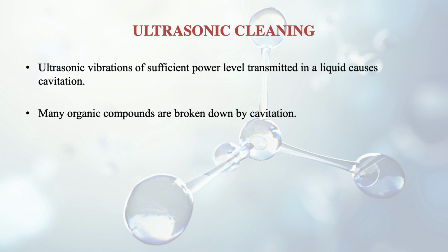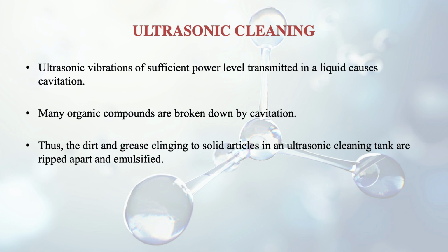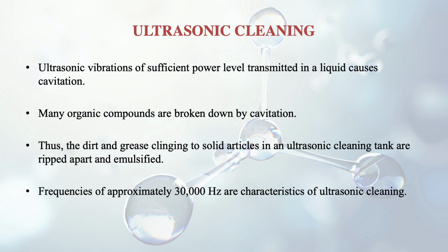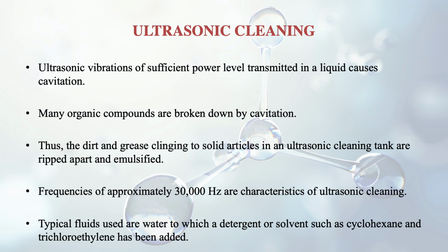You may have read about cavitation in your fluid mechanics course also. The dirt and the grease clinging to the solid articles in an ultrasonic cleaning tank are ripped apart and emulsified. Frequencies of about 30,000 Hz, that is 30 kilohertz, a very high frequency, are used in this ultrasonic cleaning. Typical fluids used are water, to which a detergent or solvent such as cyclohexane and trichloroethylene, like we discussed earlier, are mixed. So you can see that this chemical is coming in, which is why ultrasonic cleaning comes under the chemical type of cleaning. And what are the drawbacks?